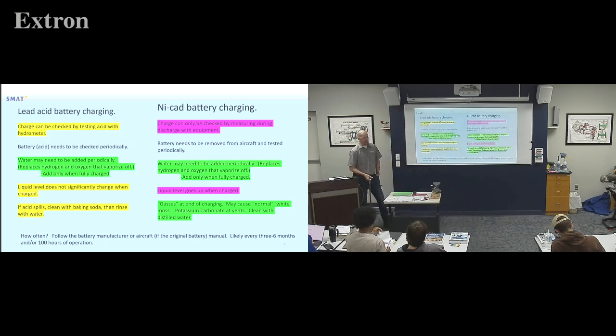discharge with other equipment. The reason is they can get that voltage memory, or it can have problems on the inside of it. So there's not a real great way to be 100% sure if that thing is all the way charged up or not without basically equipment that you can run the charge out of the battery and measure the amps for a certain amount of time. So this one we check with a hydrometer, that one you pull out and you check on the bench.